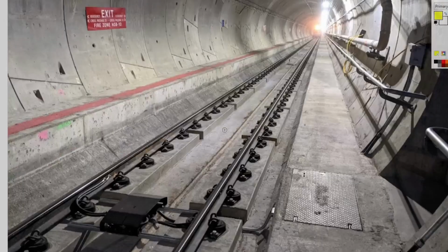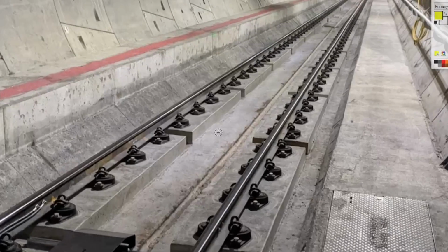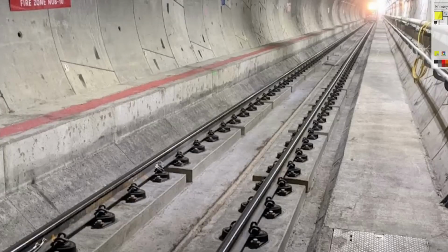There's also what we hinted at earlier with direct fixation track. And this is where, rather than using ties, the rails are directly fixated to the ground at a preset distance. These types of tracks typically need less maintenance because there's no ballast that needs to be replaced or tamped, and things are typically more rigid, but at the same time they're typically only seen in transit because the right-of-way cost is significant to pour this much concrete and use these many rail anchors.